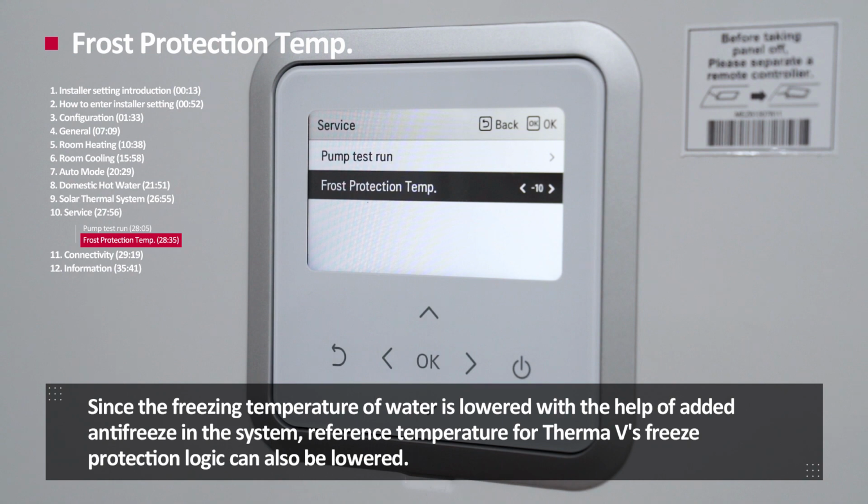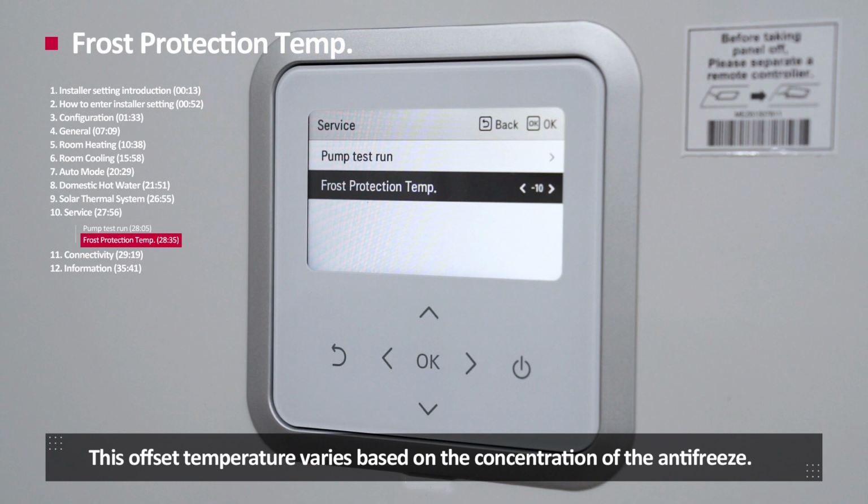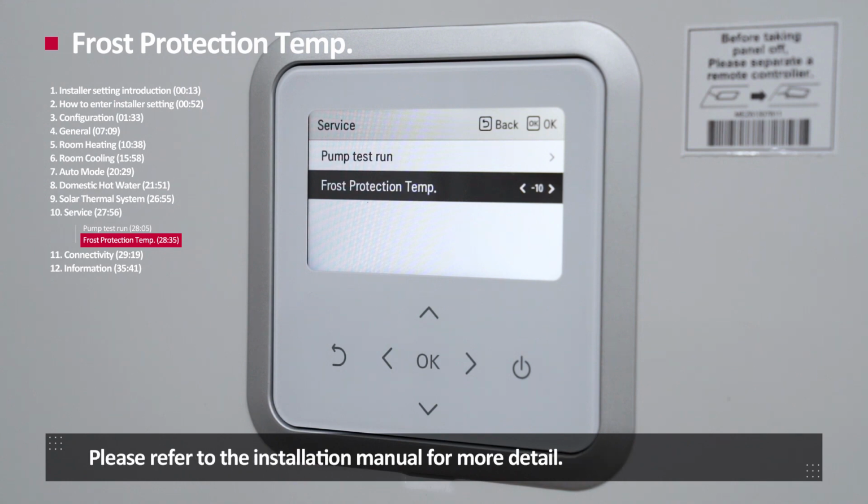Since the freezing temperature of water is lowered with the help of added antifreeze in the system, reference temperature for Therma V's freeze protection logic can be also lowered. This offset temperature varies based on the concentration of the antifreeze. Please refer to the installation manual for more detail.